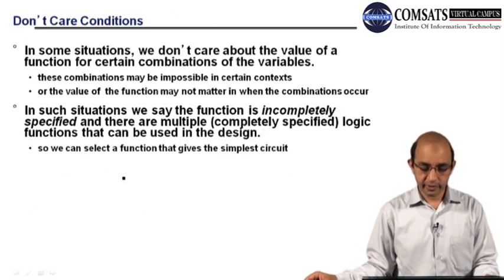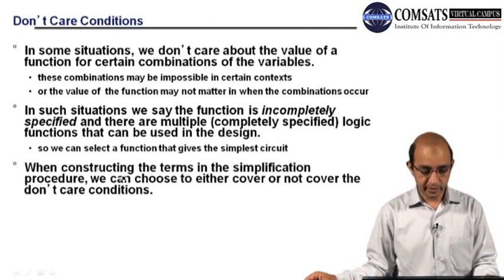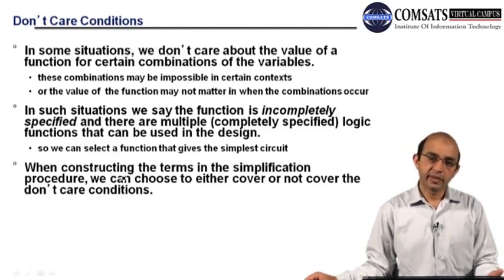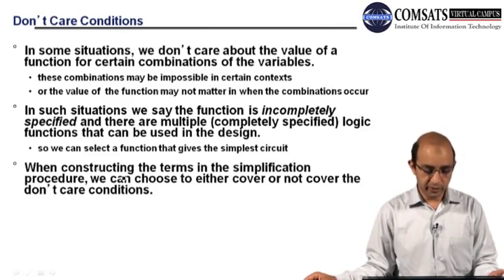So this is the same stuff, with some tips regarding don't care conditions. You can use the don't care conditions according to your design. If it can assist you in simplification, you can replace it with 1, or you can take it as 0 if it is not helping you in simplification.